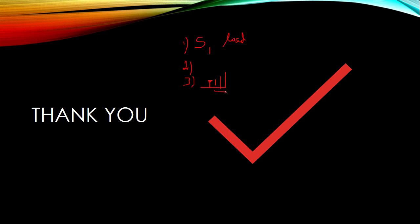The second one, intermodulation distortion. It is because when two input frequencies are given very close to each other, not only do the two frequencies get amplified, but in addition to them, we get extra frequency bands which contribute to intermodulation distortion.